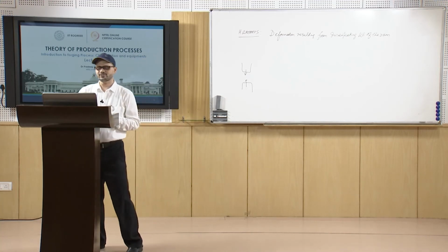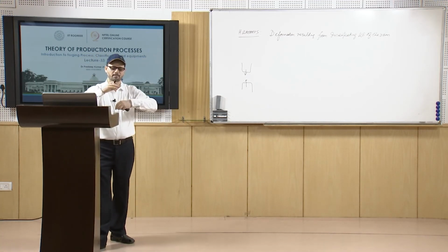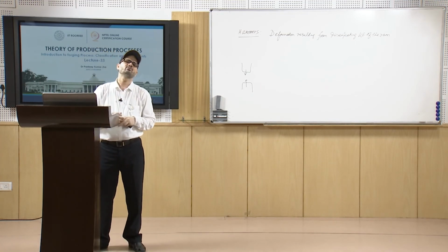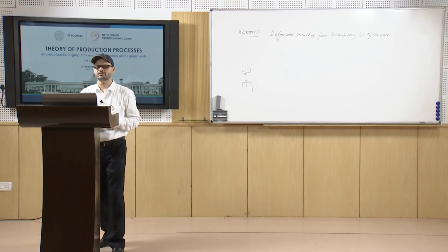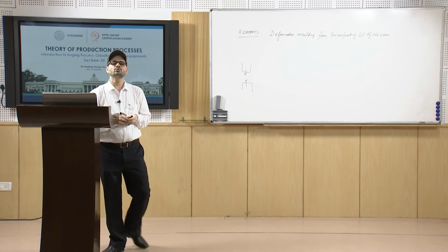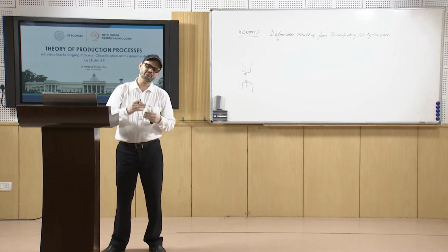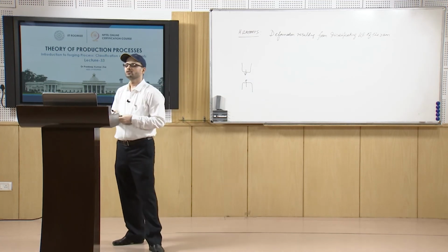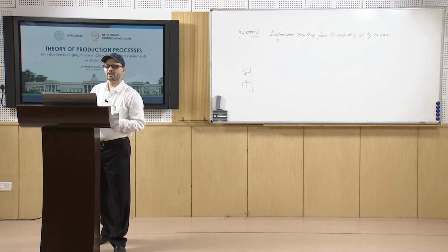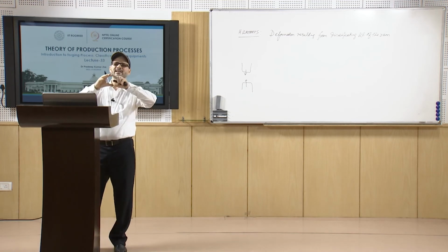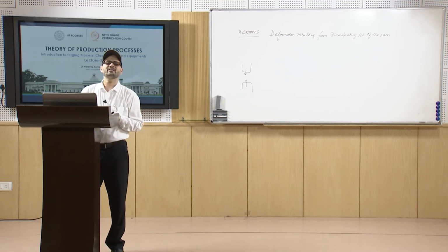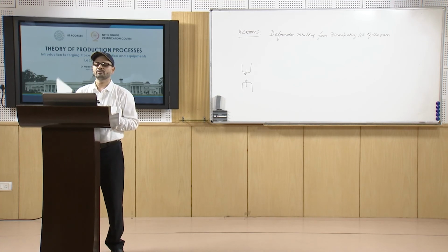At higher temperature you require very low forging stresses, that is, low flow stresses, so you are doing the forging at a very low stress. Normally the die will be made of nickel based alloys, and flow within the cavity is quite improved because of this kind of forging process.